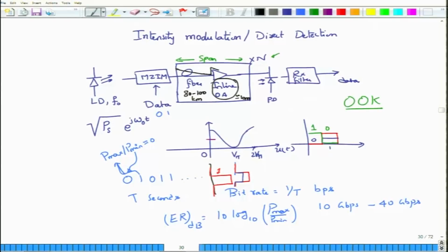So now we have propagated these optical pulses. Of course, these optical pulses are not going to stay in their time slot. Because of the inevitable dispersion, these optical pulses will start to broaden and interact with each other, so that the output would have a lot of dispersion. Because of dispersion, you will have what is called inter-symbol interference, and you want to compensate this inter-symbol interference. Now that can be done at the output end, that is at the receiver side, or